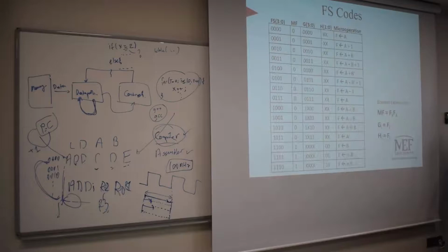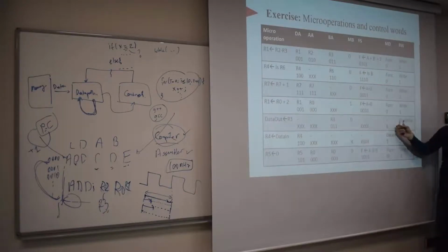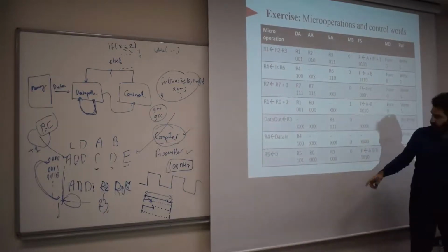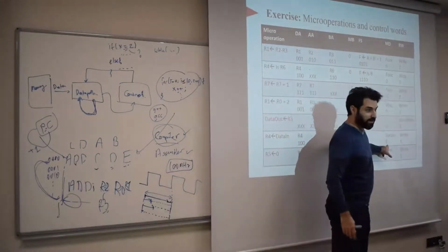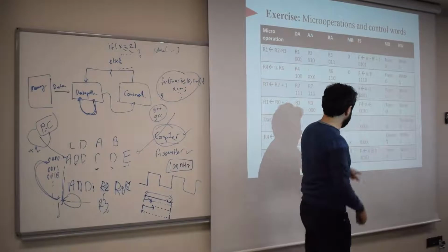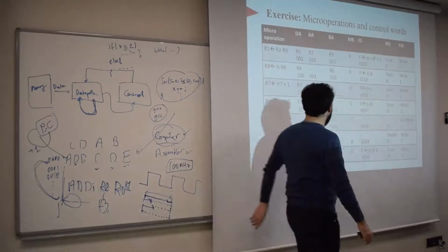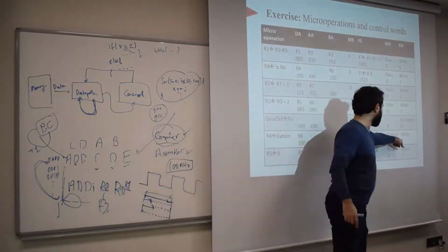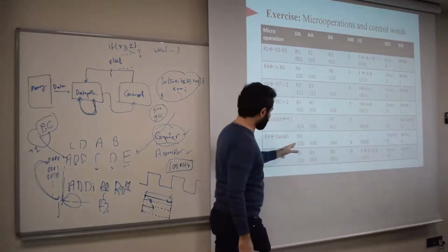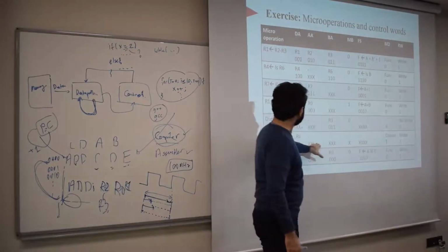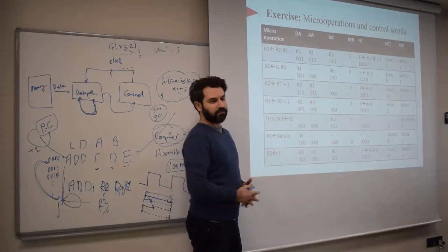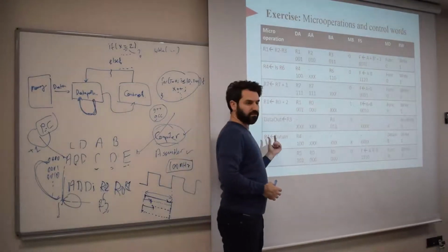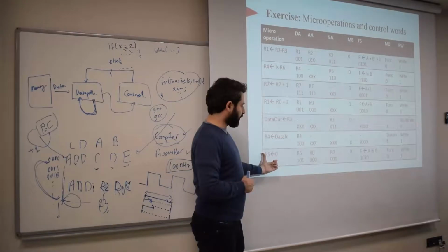Okay, so here, you got this. The read operation is different because now you have to have MD be 1 because you're reading something from the memory. That's why MD is now 1. And you're writing something to the destination. That write is also 1. But the rest of them are all don't cares. You can see that. Except R4, because R4 is where you're writing the data. That's your destination.